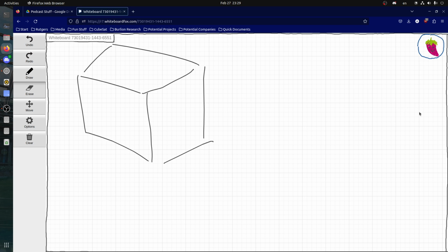If you need to point exactly north, you can just put a magnet torquer that will have zero torque when it's pointing exactly north, and then just leave it on constantly. Your spacecraft will almost always be pointing north with a bit of error, but if you don't have a pointing requirement, then that's fine.